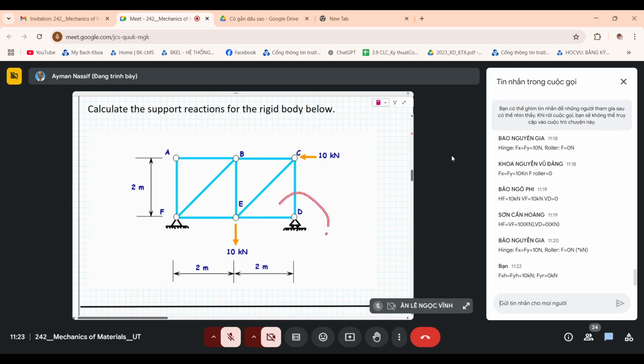So it is impossible to have any vertical reaction here. So you need to also think, as well as calculating using the mathematical formulation. If you have any vertical force here, rotational equilibrium at point F will not be achieved.